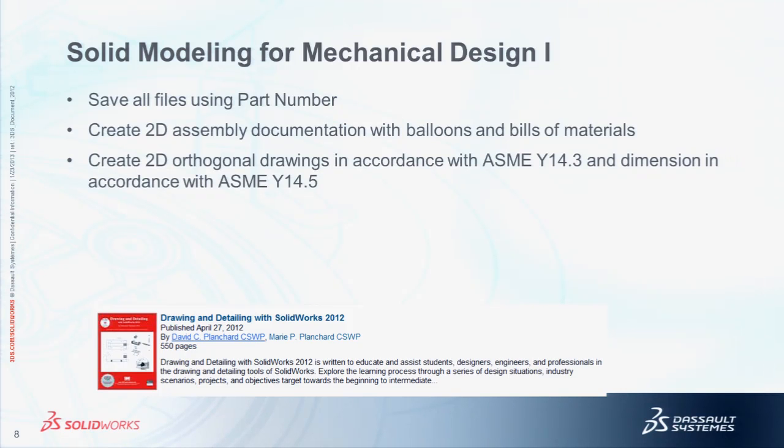Views, that's always another interesting thing. You can make a solid, go in to make views. Students will put views all over the place. They'll make the front view a different scale than the top view, and you start going crazy. So whatever you do, and I don't like it, you better get those specs out and show me that it's allowable. And obviously that same thing applies with the dimensioning. So we really push that a lot.